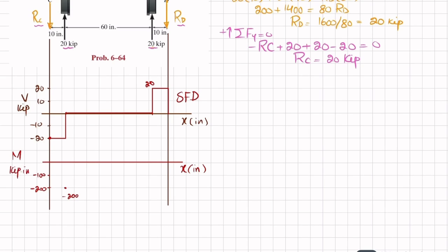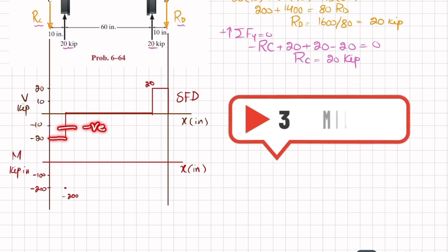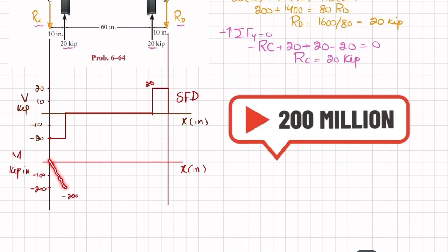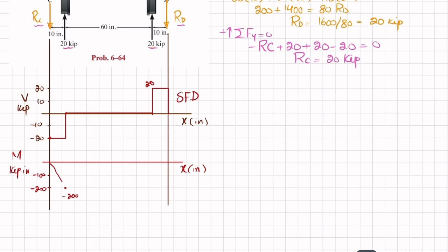Now you can see shear force is a horizontal line with 0 degree, and this area is negative. So bending moment will be 1 degree higher. It will be a first degree line, and slope will be decreasing. So we'll get this line. Now you can see that the shear force here is 0, so bending moment will remain constant till this point. Clear? So I will make it a flat line because it will be constant.